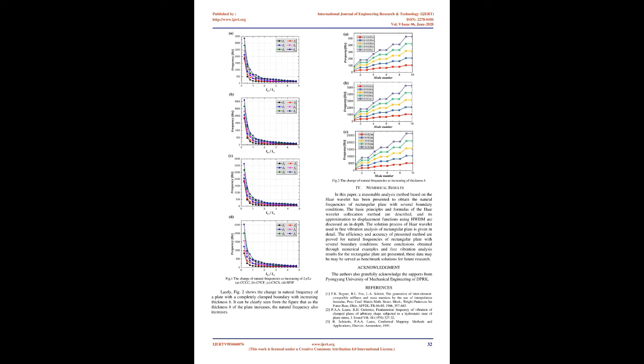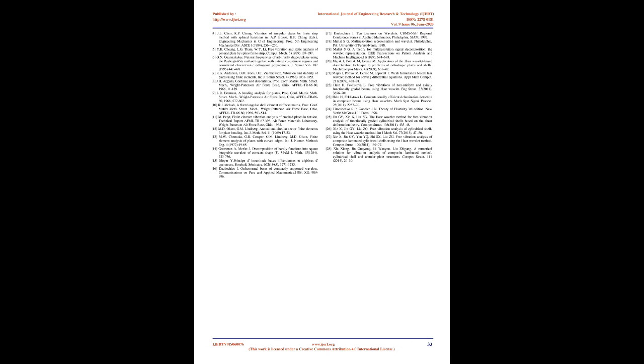It can be seen that a small number of matching points can achieve good numerical accuracy, and with the increase of the scaling factor j, the numerical results are getting closer and closer to the literature 24, thus proving that the structure is solved discretely using Haar wavelets in both directions. The natural frequency is feasible, and the boundary conditions can be accurately applied, which proves the feasibility of the method and provides a basis for the use of this method in more complex structures.